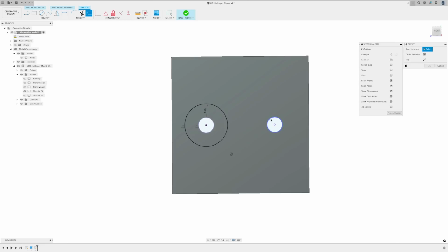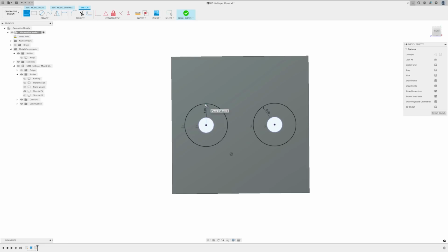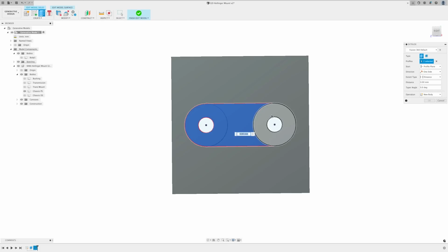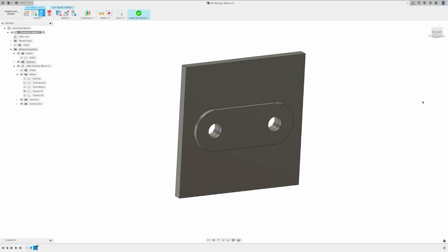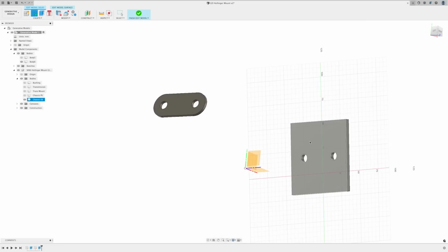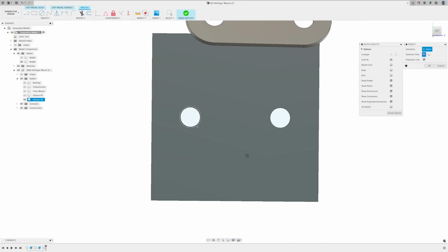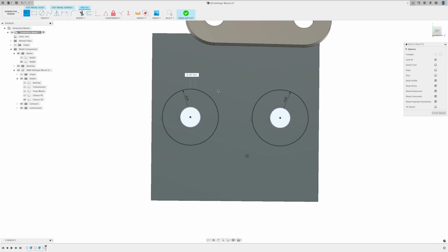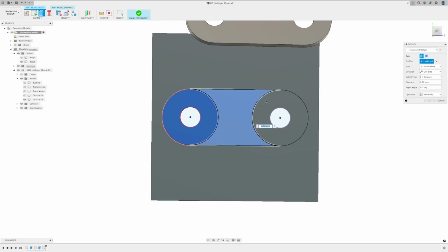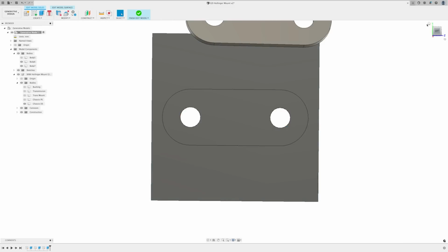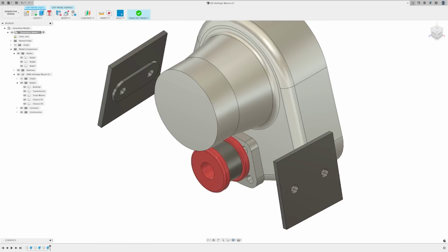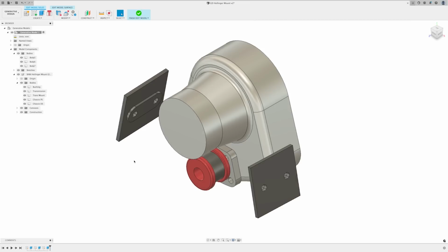We can model a simple cylindrical sleeve 1 mm thick around the bushing for this purpose using an extrude or revolve. We should also preserve geometry around the chassis mount holes to ensure we can actually bolt the solution in place. Let's make a 3 mm thick plate on each side that the hardware can fix through. We'll use the project, offset and line sketch tools and then a simple extrude to do this, making sure these are new bodies so we can use them separately from existing geometry. We'll also be able to use these in a few moments for our structural constraints.